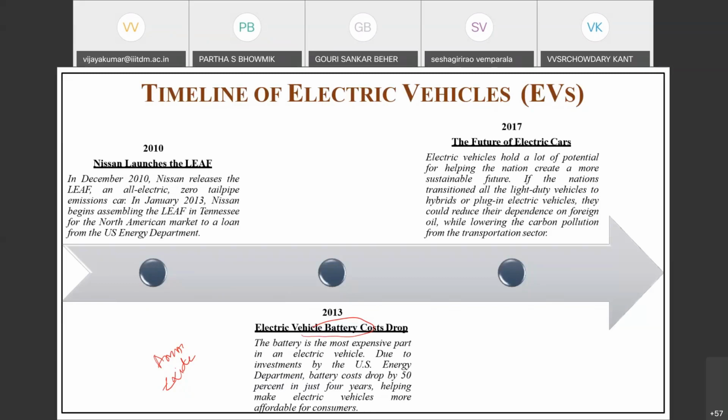When you are connecting your vehicle to the charging station, for example, in a commercial park-and-charge setup, or at your home where you can park your vehicle in the parking lot and charge it, during the night you are connecting your electric vehicle to the network. If your battery gets fully charged, your battery can act as an energy storage for your distribution network. For that purpose, we need aggregators. The aggregators can aggregate all the electric vehicles connected to the network, and then aggregate that energy storage.